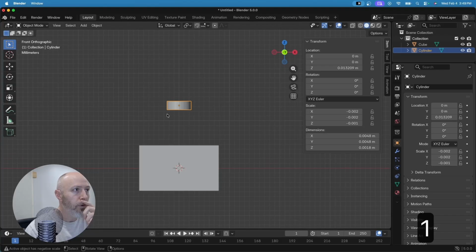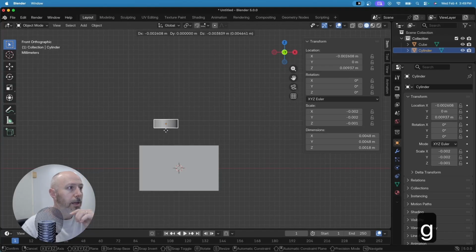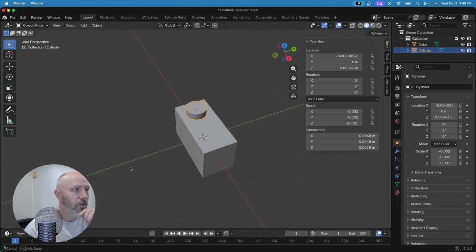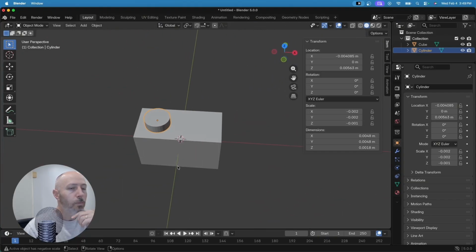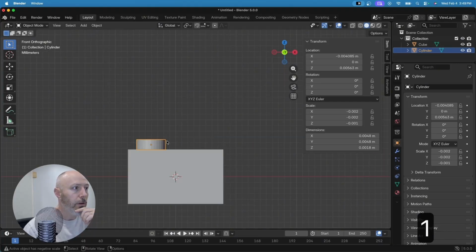So when we're just aligning things, now I can kind of visually do this, and it's probably pretty close. Well, we're not going for pretty close. We're going for machine accurate. Pretend that we are making the model that is going to be shipped to the factory that is going to produce these bricks. And Lego, if Lego is our customer, they are not going to be happy with this unless they are completely spot on. So what are the things that we need to worry about? First of all, we need to worry about our vertical height.